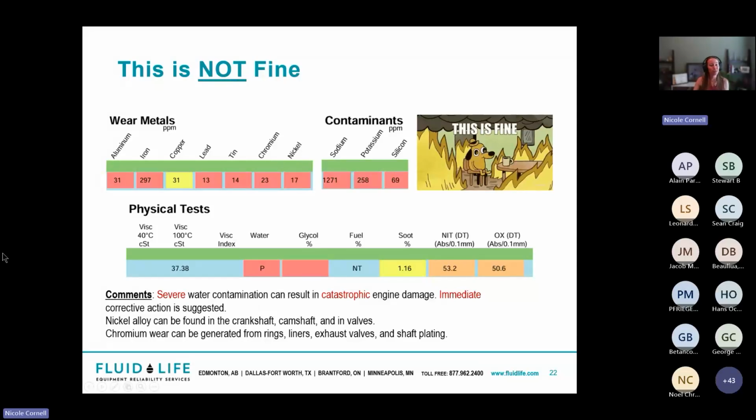So after the PM received this, he pulled the unit from the field so he could do some maintenance work. Since the oil was contaminated, he did an oil change, scheduled some inspections, and even started ordering parts because he predicted that a failure was coming soon. Before he did a complete overhaul, he did have the technician take another sample to try and establish a failure trend. This time, when the results came back, the report came back clean.